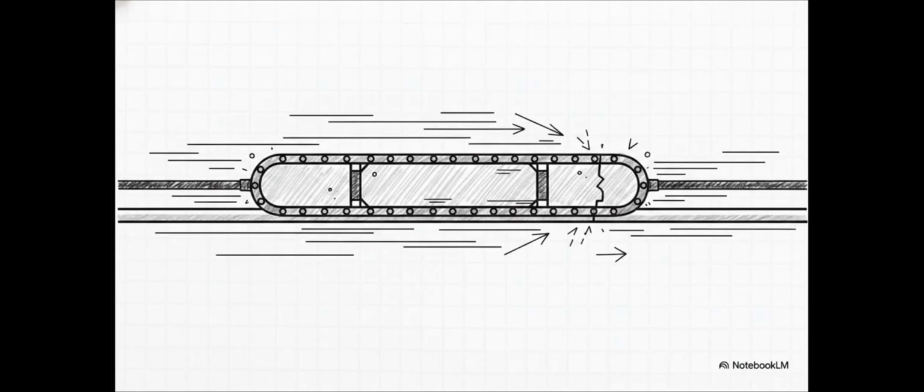On the flip side, you absolutely must choose continuous flex if the cable is going inside automated drag chains or CNC machines. We're talking about machinery running 24/7 at incredibly high speeds and accelerations. Here, your primary risk isn't navigating some tight corner. It's the sheer mechanical fatigue from millions of identical, repetitive, linear movements. Continuous flex is basically mandatory to survive that kind of relentless punishment.